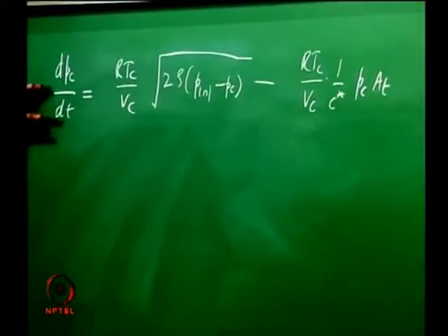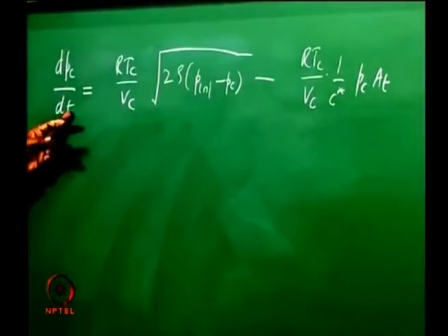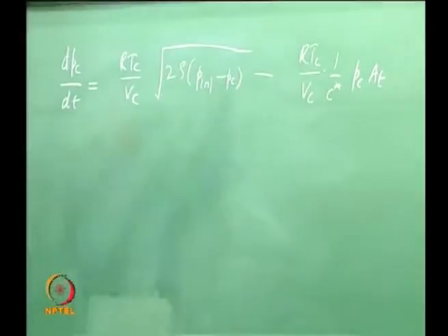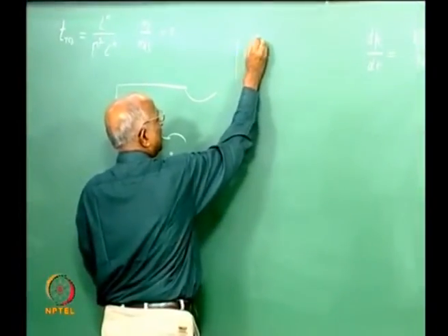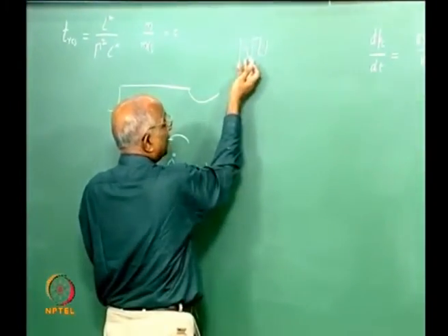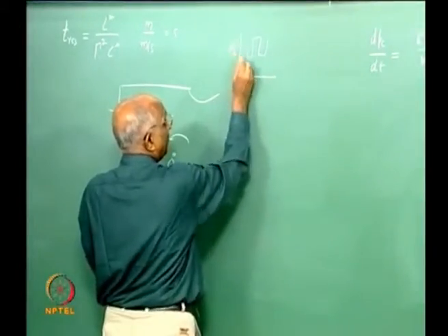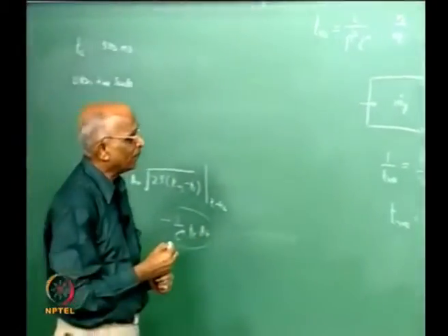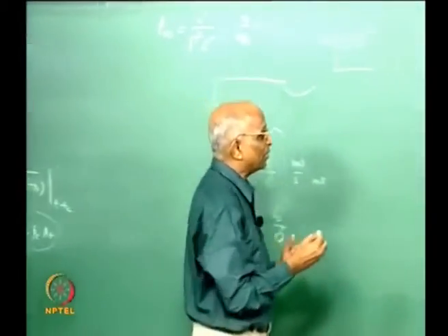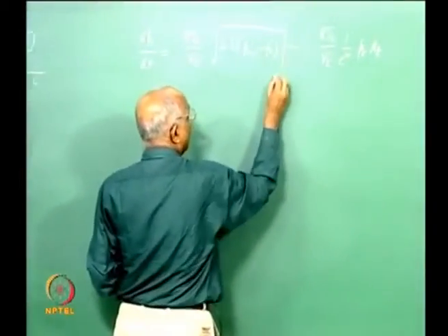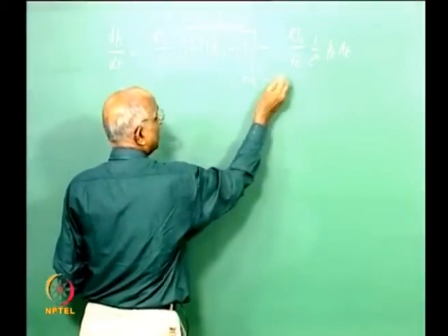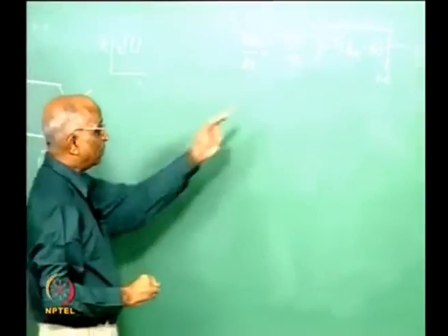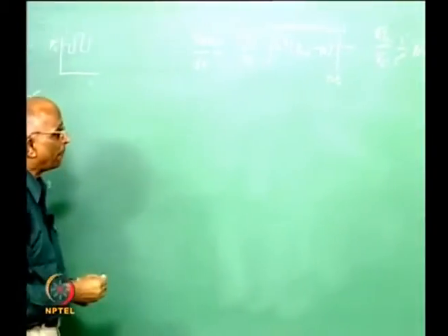Essentially what is it we are looking at? We are looking at the variation of Pc with time. We are trying to see, whatever we studied just now with the numerical example, we found under some conditions it goes like this. What is the rate at which pressure changes with respect to time is what we want to predict using this equation, and precisely that is what I am solving for. But we also note something here, which is very primary: this happens T minus Tc before this, therefore this is a function of time. Therefore, Pc is also at time t over there.